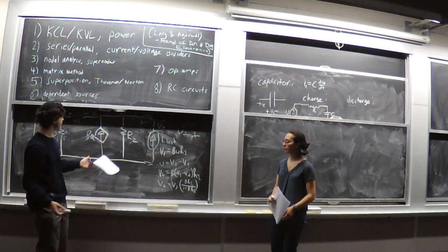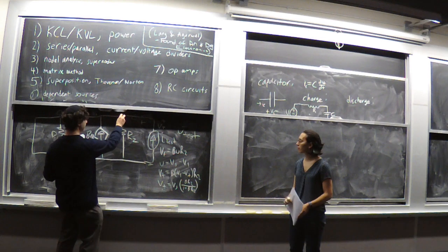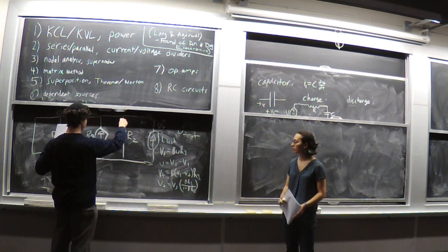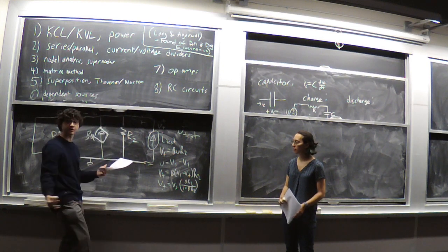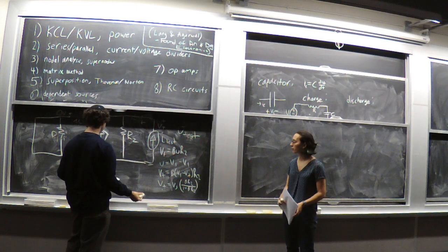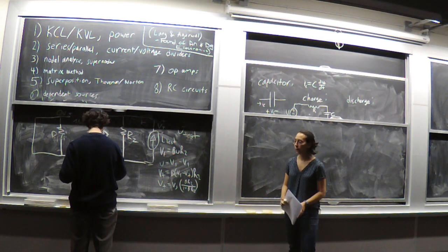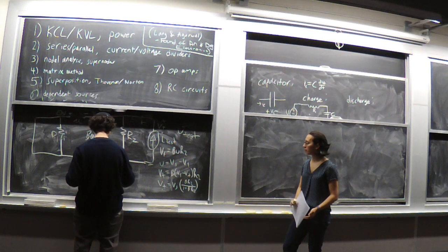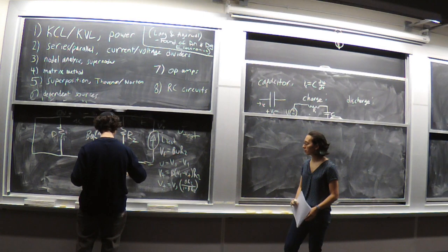In terms of this side, if we do KCL at this node, we have these two current sources going up. They're both going to converge here, and then it all has to drop across resistor R2. And so that voltage drop, which is precisely V test, gives us VT equals R2 times (VU plus I test).